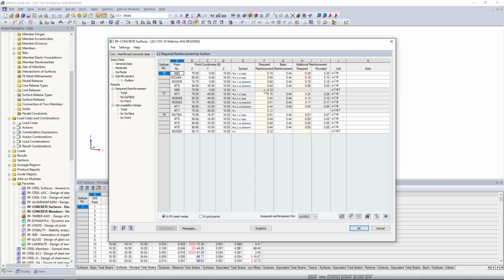And now notice, actually, we've improved the shear design. We no longer see that non-designable, but we've also improved the longitudinal reinforcement because we had high stress, high singularity and internal force concentrations at those column locations, even for bending. So this really improved our design quite a bit. Okay, so that really sums up the overall surface design.